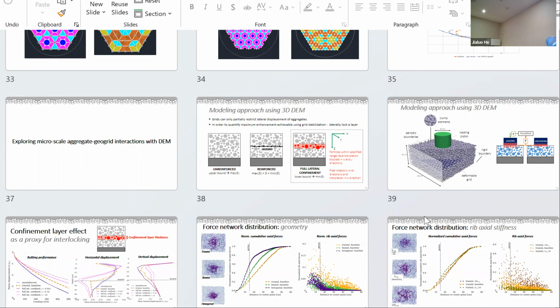One of the things that, again, I think is important to think about when we're reinforcing a pavement is that, by and large, except for maybe a few drunk drivers, most of the vehicles pass down a certain path within a certain lane. Yeah, they change lanes from time to time, but by and large, compared to the total number of wheel loads, they're in a certain area. So we don't recognize that when we use a geogrid that is distributing everything uniformly. So for example, can we come back and not be so tied?